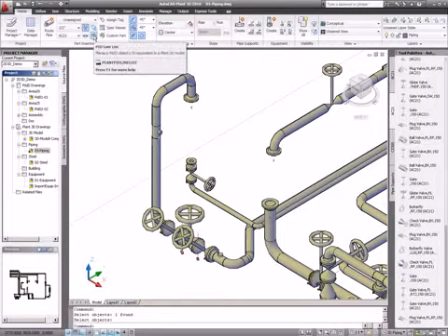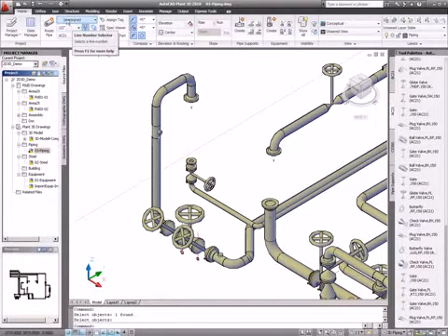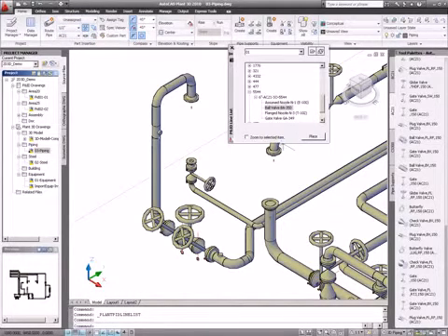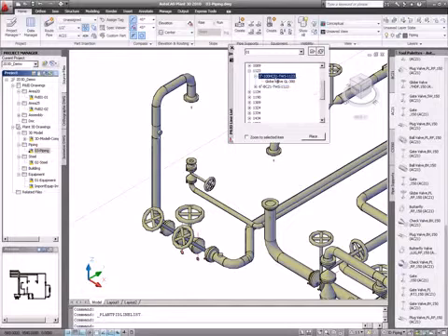So again, I select from P&ID, regardless of what it says about unsigned on the name, on the pipe. I select the P&ID list, go to the line lists, and that was 1123, I believe it was. So we look at 1123. Yes, it is. In this case, you will see some different things. The user actually selected the wrong spec, because the spec of this pipe is actually BC21, and that's the main pipe as you see here. This is 6-inch. Then we take a look at the 3-inch, and if you then place it, because the user didn't type the correct spec, then let's see what's happening or how you can change it.